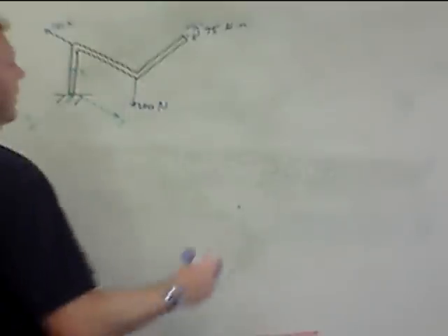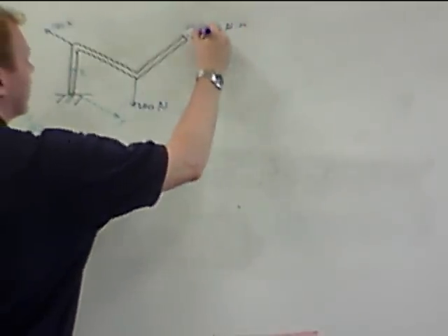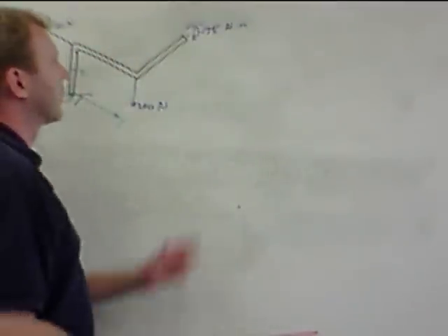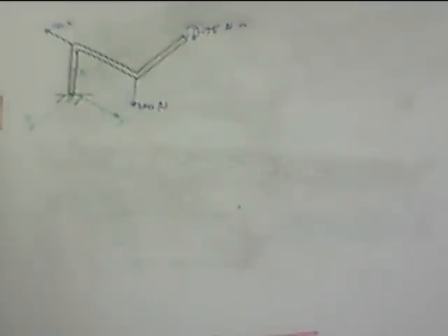As I've drawn it, looking from the positive x, it is rotating clockwise, so we'll make that negative for a clockwise moment around the x-axis, giving you a minus 75 Newton meters. Again, the 75 is given the minus; you have to be able to tell from the direction of the arrow.